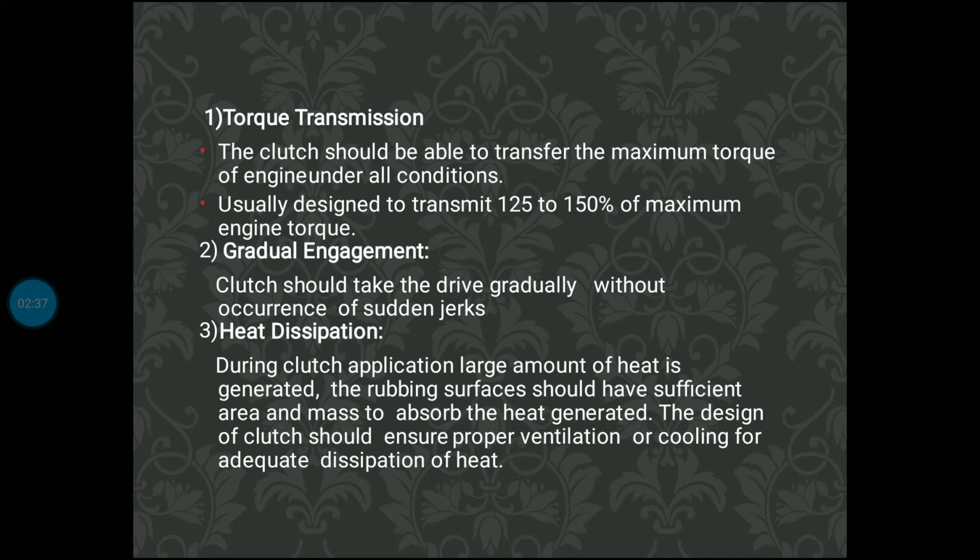The clutch should take the drive gradually without sudden jerks. Whenever I press the clutch, the engagement must be gradual. If there is any up and down, a problem will happen. The driven shaft can even break. So that is gradual engagement.